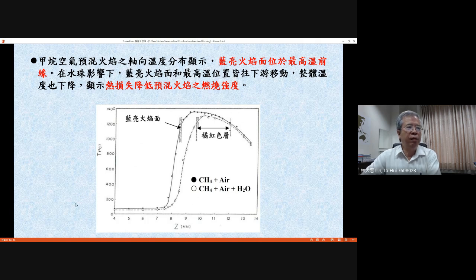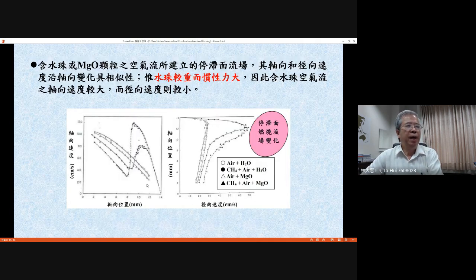You can use these positions to do the measurement of actual velocity and use this velocity to represent the upstream velocity, and this upstream velocity is just balanced with the flame speed. Which means in your experiment for a given flame, you measure the temperature up to the point ready for the increase in temperature. At this point you do the measurement, and you can use the actual velocity, the normal velocity to the flame surface, to represent the flame speed. Okay. By this consideration, somewhere here you can use this value, maybe around 30 centimeter per second, to represent the flame speed of this flame in your experiment.